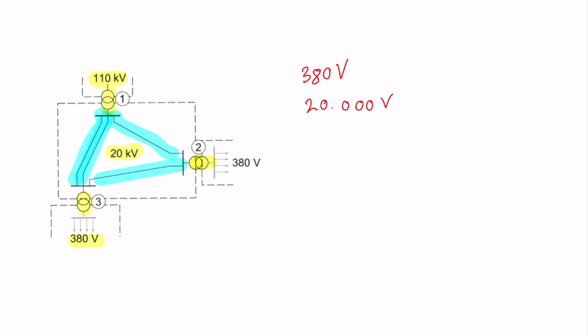They can cause some numerical issues. The computer is solving most of the problems of computing what the flows through the lines are and what the voltage is at each node. For computing those values, we have to implement algorithms, and when the numbers are very different, we can have numerical issues.